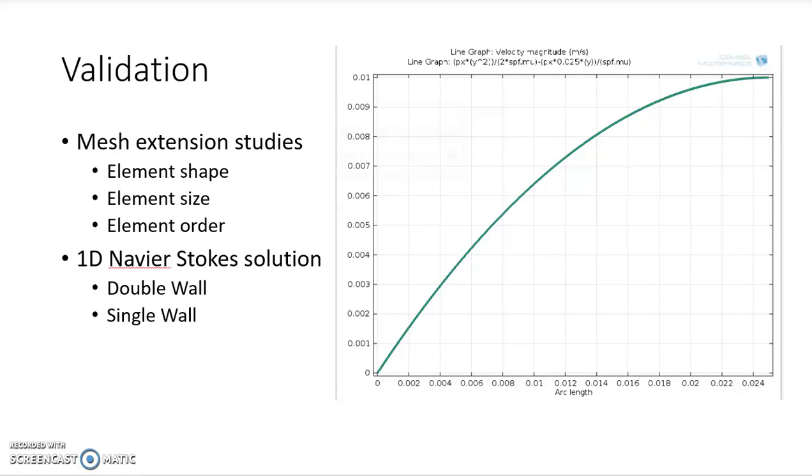Second-order elements were found to be crucial in the model accuracy, but allowed for mesh independence from element size. Model results did not vary at second-order elements at normal or finer than normal element size groupings. This also includes adequate coverage of elements over the corner and with boundary layer elements. Boundary layer elements were also found to be mesh independent at a certain size and number.